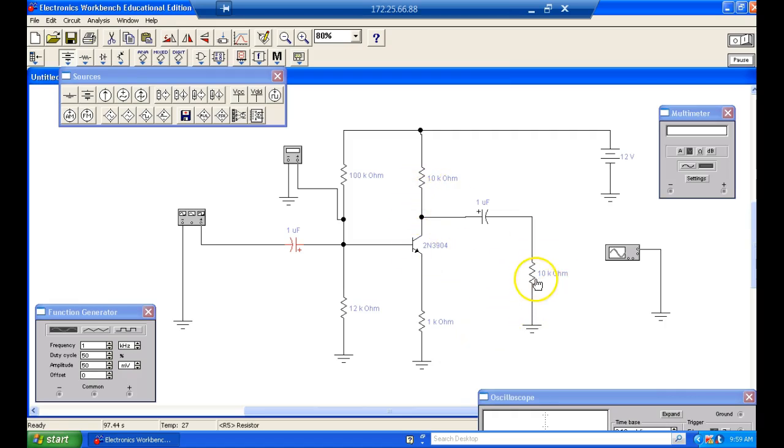You understand? Normally, so what did we use when we calculated our gain? We calculated this at 5K. Oh, I'm sorry, it will happen. So what happened? Okay, so when we calculated our bias, we ignored this resistor right here, right? Because this capacitor was blocking the DC bias. So what we're going to do is we're going to short this guy right here, and now my DC bias at this point right here is going to be set by this circuit right here.